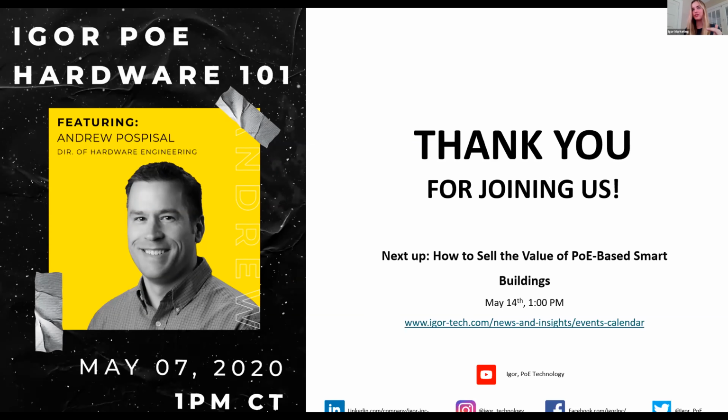All right, we've got a couple that should be pretty easy to run through in the last couple of minutes here. From Victor, will the emergency nodes work with integral backup batteries? Not yet. That was our intention with the Rev 6 line, developing an integral local on-fixture backup battery. That became more complicated than we had originally thought. We haven't given up on the idea, but right now they're really just based upon that centralized generator, UPS, or inverter backup power.